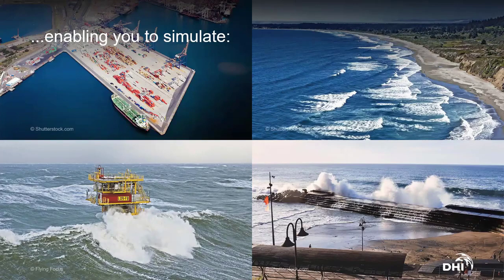It is solving the three-dimensional Navier-Stokes equations, and it is capable of solving any wave fields, such as short wind sea and long swell seas. We can even handle tsunami waves, and of course, all of the nonlinear transformations happening in the actual swash zones as well.